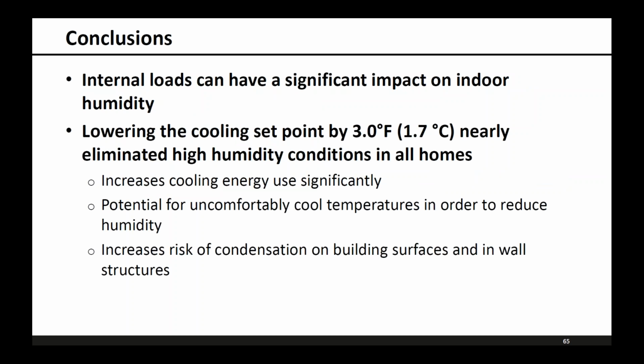So we've established that the internal loads can have a significant impact on indoor humidity, and really the interface for comfort that most customers have now is that cooling set point. So if people don't feel comfortable, they can go adjust the set point down and achieve better comfort with a few drawbacks. So we've got increased cooling energy use for reducing the set point, which we showed.